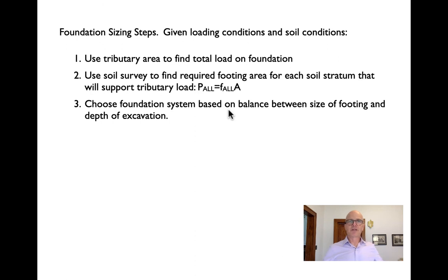The way it usually works, the shallower strata are generally weaker, so we always have this trade-off between very, very big foundations at shallow levels and very, very tiny foundations at deep levels. And that will, along with knowing the cost of excavation, the area conditions, the areas available to us on the site, help us make the decision balancing the depth of excavation and the size of the footing.